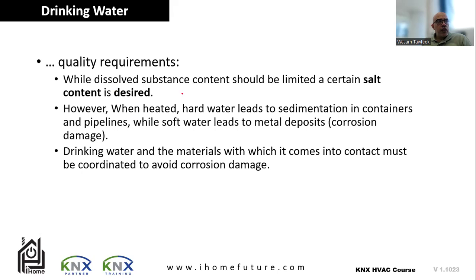What else is in the quality requirements of the heating of drinking water? Dissolved substance content should be limited. Certain salts, so maybe you can put some salt in it, okay? But you shouldn't put other materials that will not be dissolved. When heated, the hot water leads to sedimentation in containers, so it might lead to some residuals in the container itself, which might lead to corrosion of the container or the pipe itself. So you need to avoid this as well, and there are some systems that avoid that.